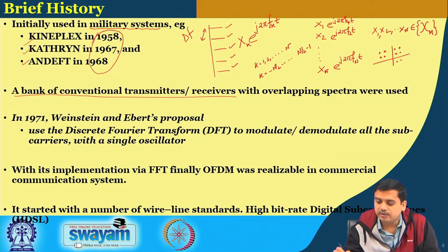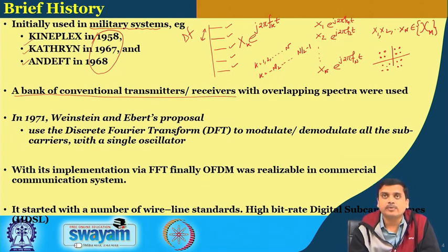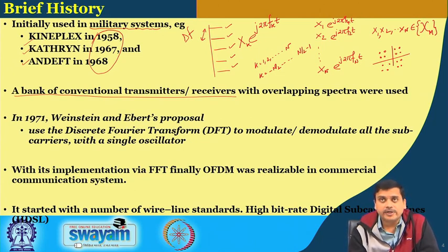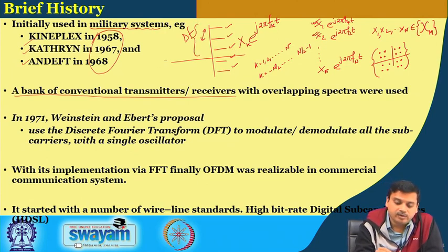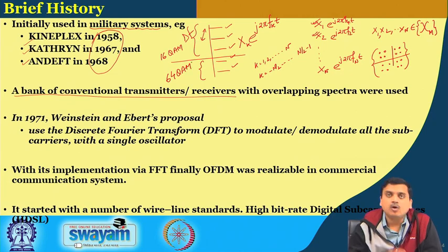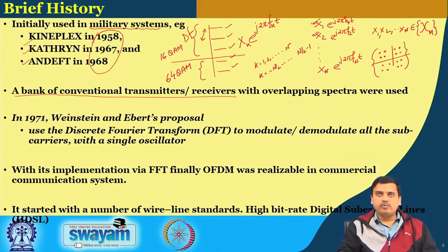Let us say we are drawing the constellation diagram for 16 QAM. Each symbol will be drawn from it depending upon the bit sequence. Now, it can also be noted that each of these symbols coming in need not necessarily be drawn from the same constellation. It could also happen that some of these carriers take from 16 QAM, while the rest of them take from 64 QAM or any other combination. So this is a generic model, a generic system layout, a generic framework.